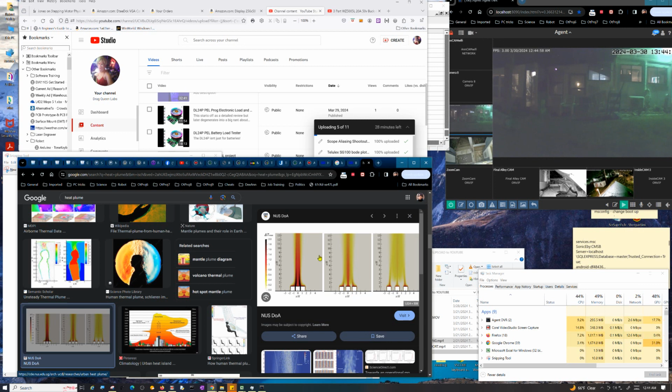And like I said, if this were a sealed enclosure, a lot of this heat would spread around, so you should probably take your measurement after 20 minutes or so, just to see what the final temperature is. Don't just turn it on and take a temperature reading in 60 seconds. Wait for it to warm up in there. And make sure too, in your room, as far as ambient air is concerned, that your room temperature is in the right environment too.